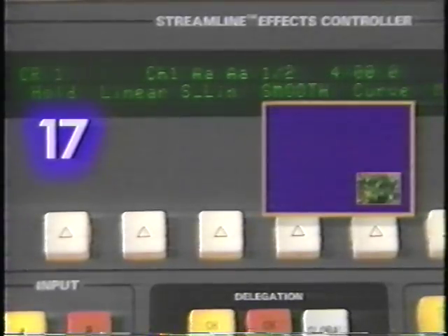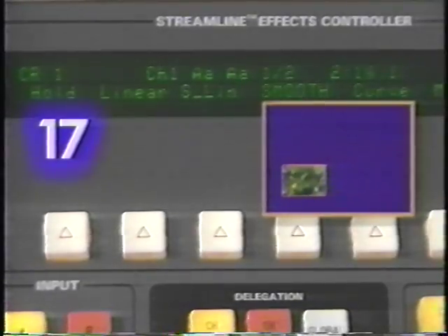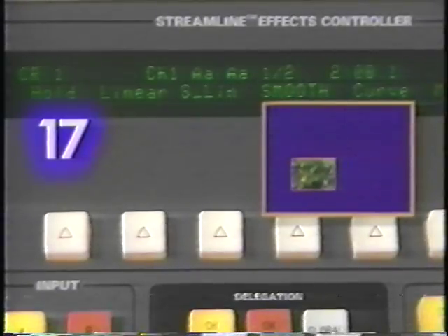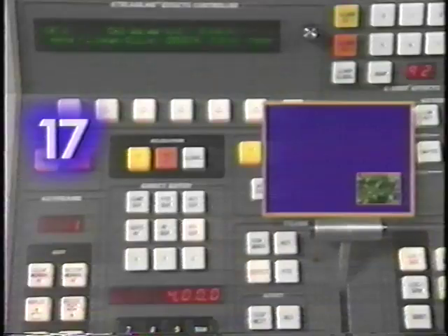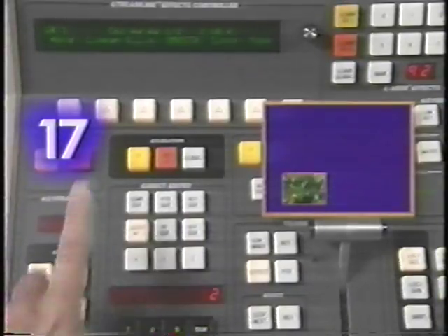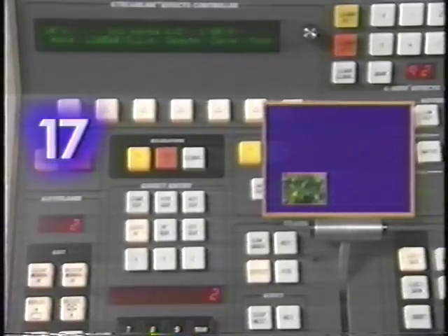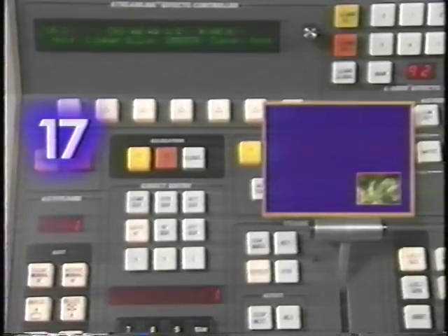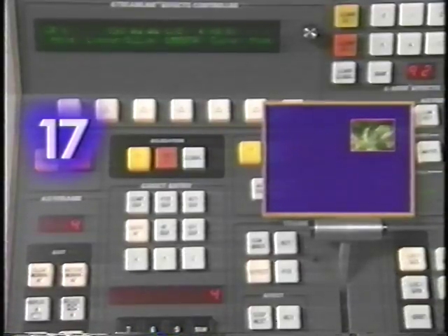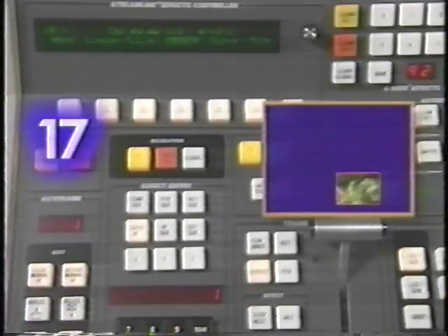When you first enter an effect, in-betweening is set to smooth as the default value. Once you've selected the parameter change formula, you can either apply it to a single keyframe or apply it to the entire effect. Go to keyframe number 2. Select Linear and press Replace. This will cause the location and center of orbit parameters to change in a linear fashion at keyframe number 2. Rewind and run your effect. Notice how the parameter change at keyframe number 2 differs from the change at other keyframes.